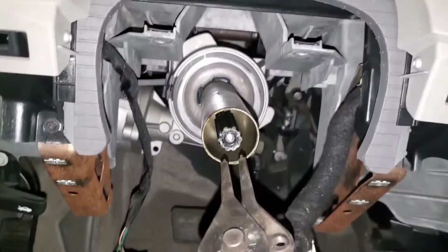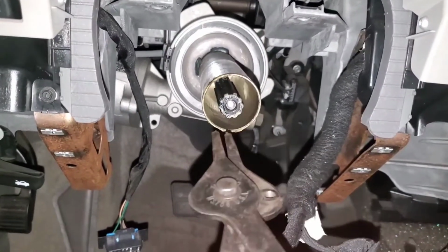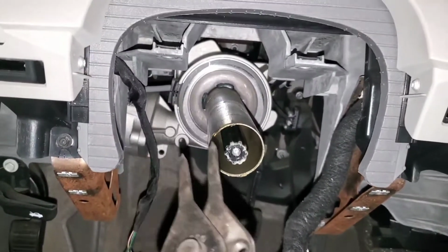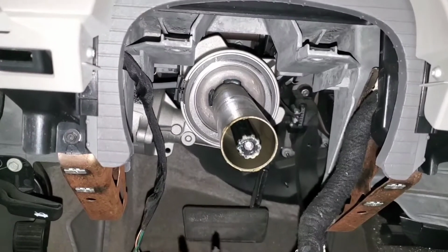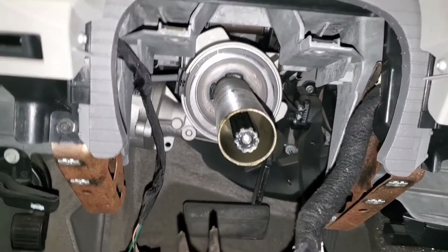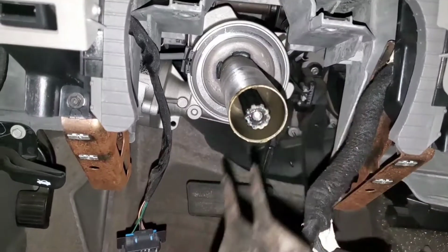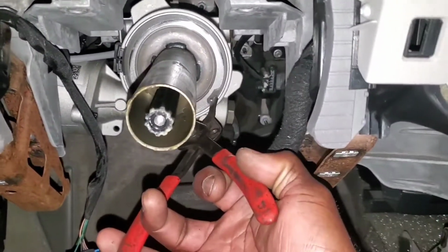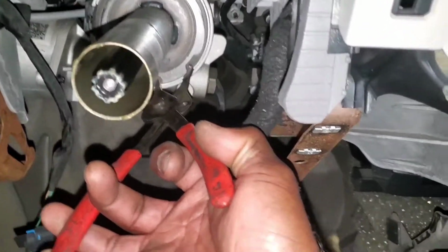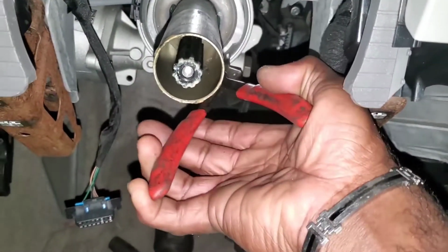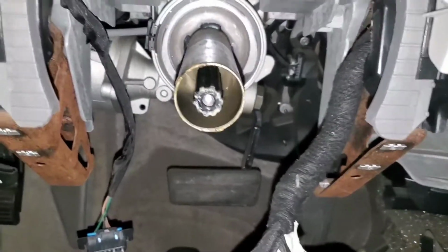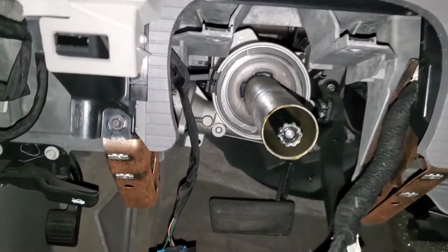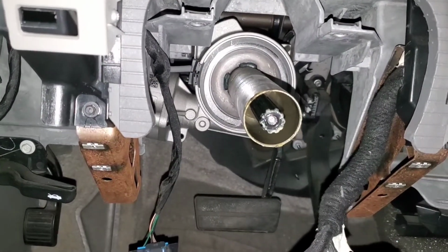So basically, between this side of the steering input shaft and the output shaft there, this torsion sensor, this torque sensor, is measuring the difference in the twist, and I guess that shaft is calibrated, so depending on the difference between the two numbers, it knows how much resistance the steering wheel is receiving and how much assist the motor needs to provide.